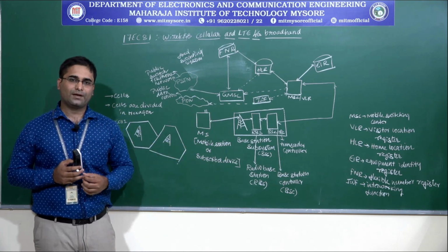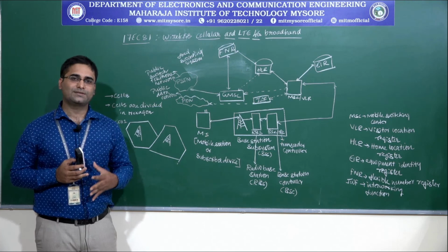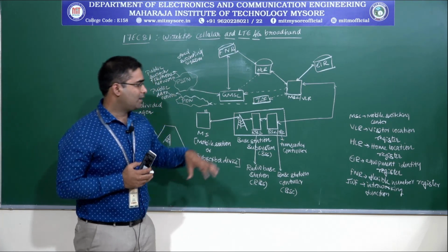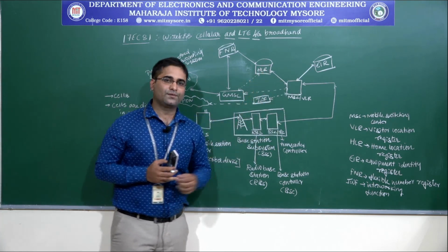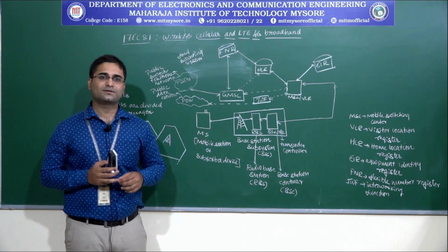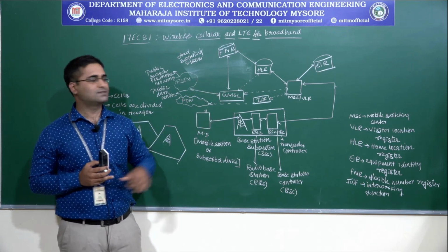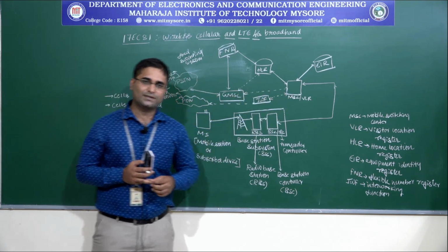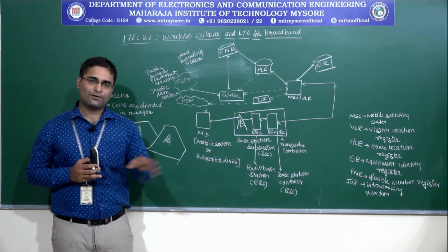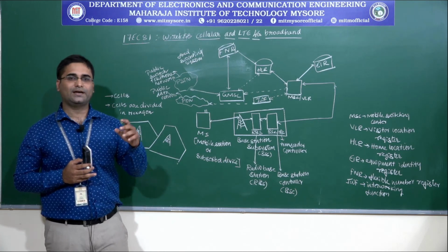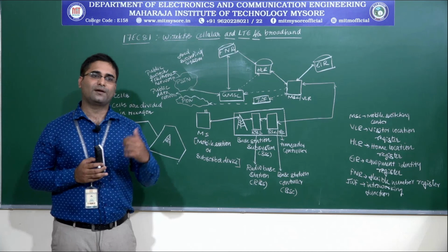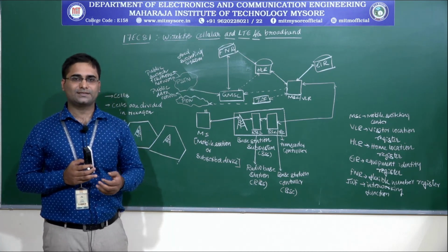In order to perform the rate adaptation with respect to the signals, we have the transcoder controller, and for the updation of the signal, we have the servers or databases or registers. We call it the MSC, the mobile switching center, which is the heart of the telecommunication system, where it defines the setup and routing of calls to and from the sender and the receiver.